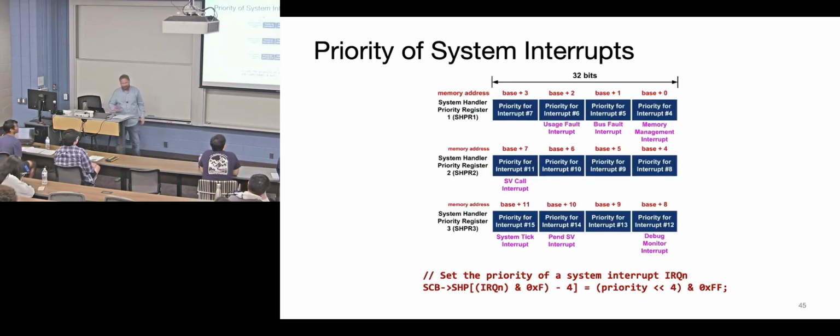And you can refactor that into, when you look through your CubeIDE code, you're going to have some register value, and you can put all 32 bits in there if you want, or you can write byte-wise or half-word-wise or whatever you want. There is probably no data actually able to be stored in those lower 4 bits. It's just not going to be implemented at all.